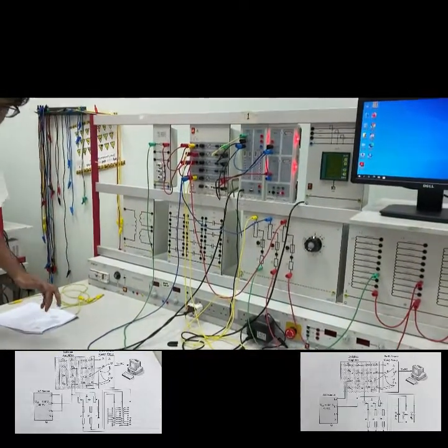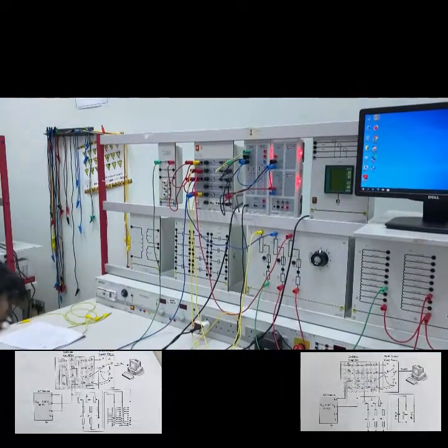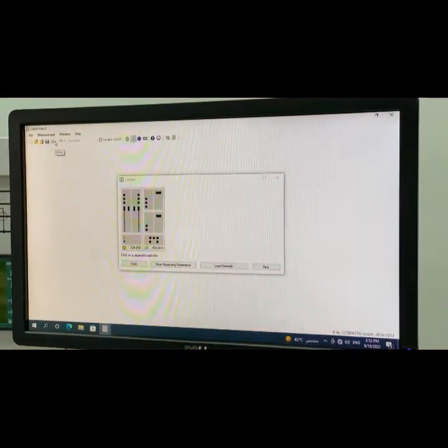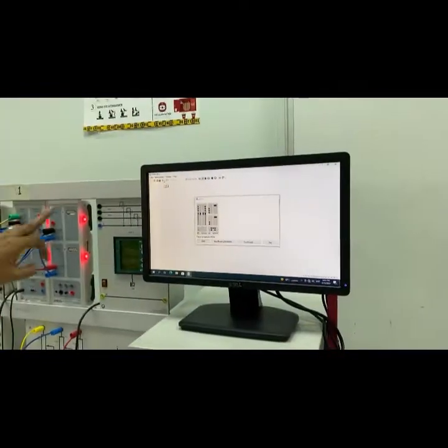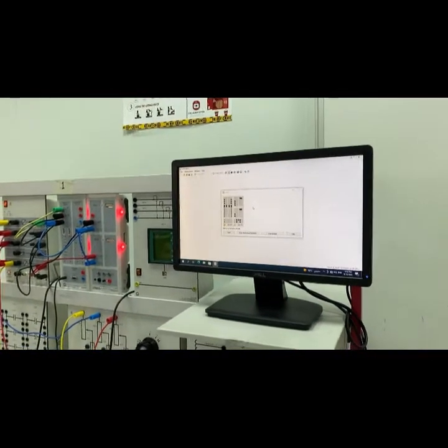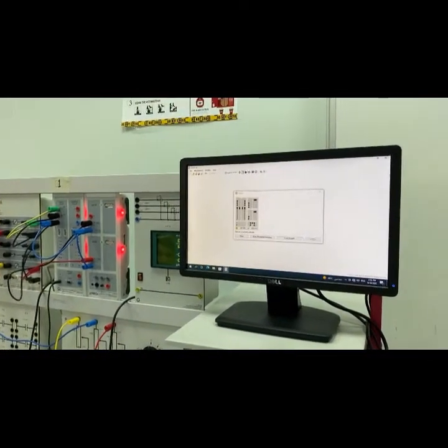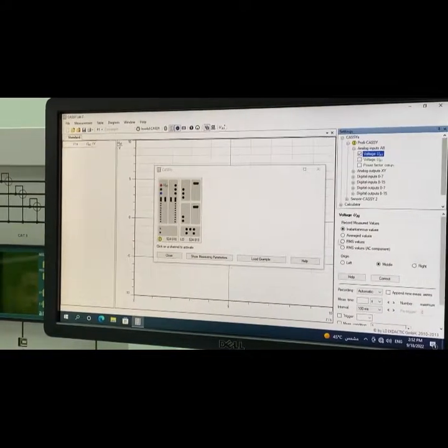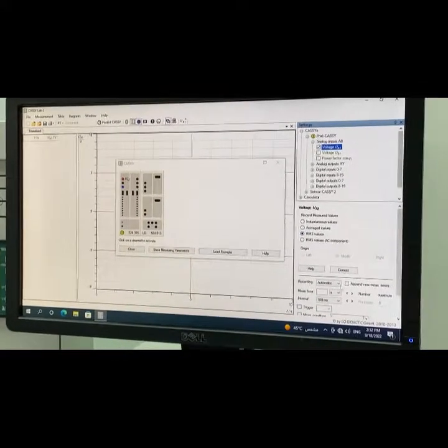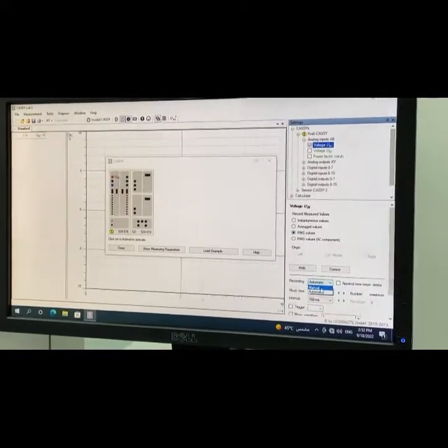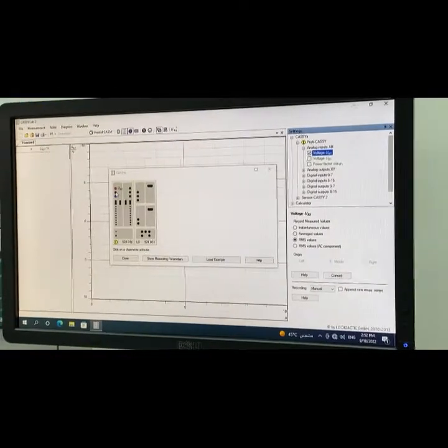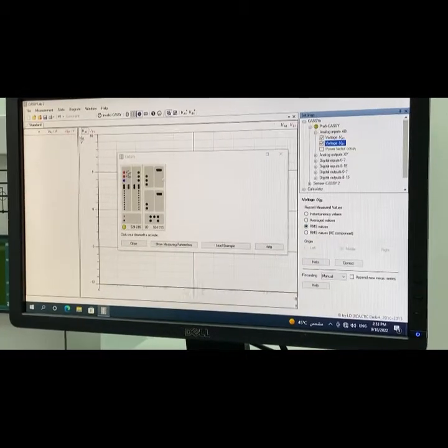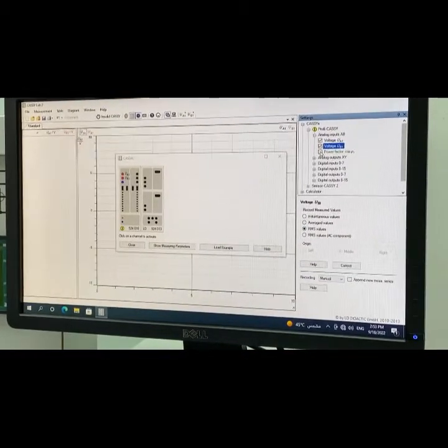Now I will take you to the Lab software. You may come a bit closer. We entered into the software, and make sure that all the lights are on over here, otherwise this screen will not appear. Now how many channels do we have to activate? 4. This one is channel A, we activated it, and because this is AC, it is RMS. We'll put manual at the beginning. Second one is channel number B, we activated it. This is average value as well, and you select here power factor cos theta 1.